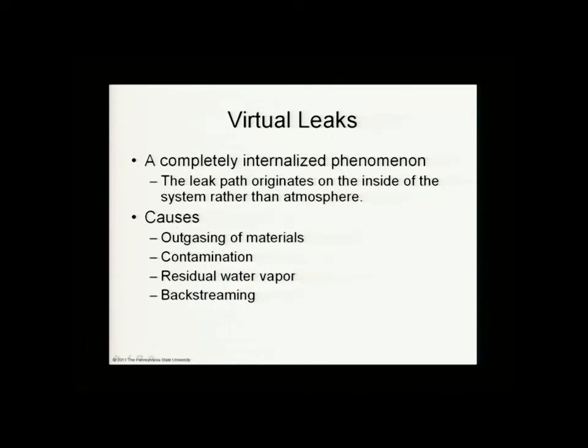Contamination, we said that some of it can turn into a vapor going into the vacuum system. You can have residual water vapor that you just have a hard time getting rid of. And then you can have backstreaming of oil. That's another source of a virtual leak.